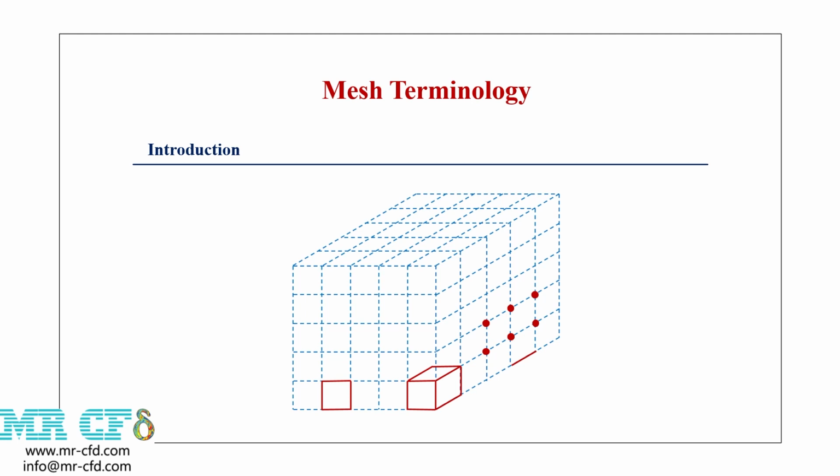In Fluent software, each computational mesh is divided into a series of control volumes. These control volumes represent cells that are enclosed by faces and nodes. Fluent software uses internal data structures to define the domains of the mesh, assign commands to cells, cell faces, and nodes within the mesh, and establish connections between adjacent cells.